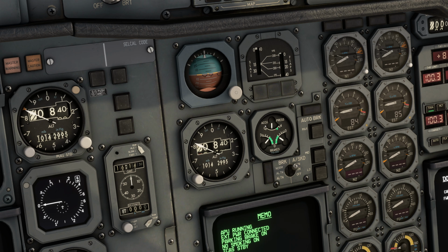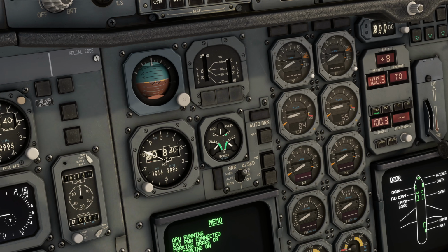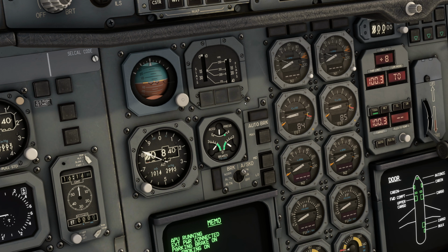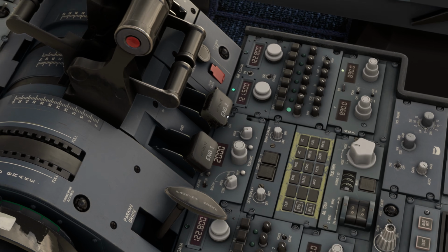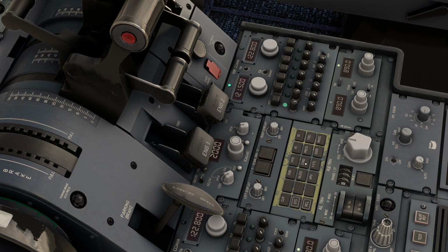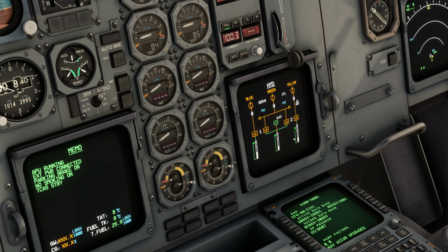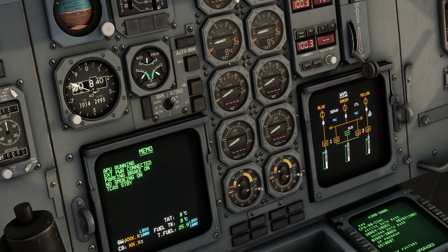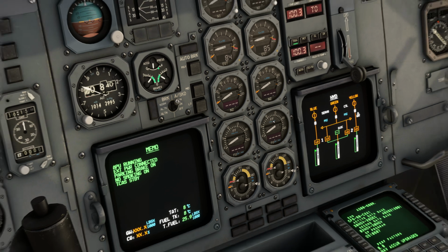Now, after you've done this check, you will notice that the accumulator pressure has reduced quite a bit. The reason for that is that the hydraulic system is not powered at the moment. So if this is getting into the rather low side, by default you should have 7 applications, but it can be less based on experience with Airbus aircraft. So if you want to recharge this, there's an easy way to do so. The system is connected to the yellow hydraulic system. So over here, if we want to pressurize or refill the accumulator brake pressure, we just need to power the yellow hydraulic system.